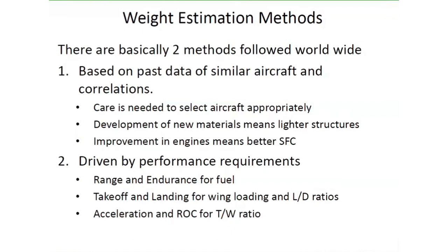However, you have to ensure that you're taking data of similar aircraft. If you're designing, let's say, a combat airplane similar to Rafale or Tejas or F-16, there's no point in collecting data with respect to Airbus and Boeings. Similarly, if you're designing a passenger aircraft, there's no point in looking at data from the F-16, F-14 and so on. So you have to appropriately select aircraft which are appropriate to the design you are developing.